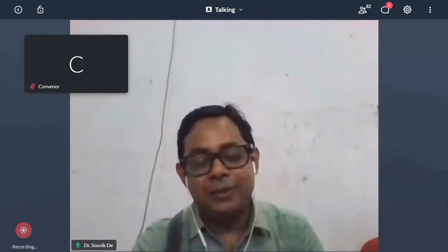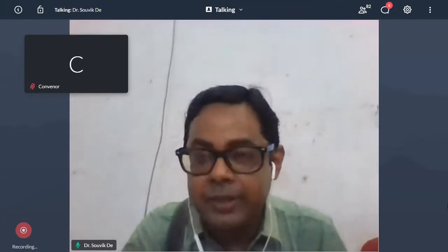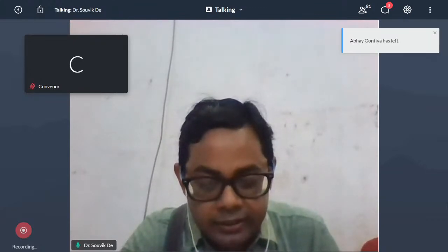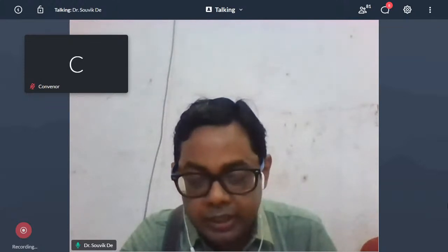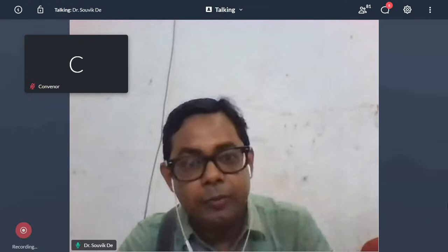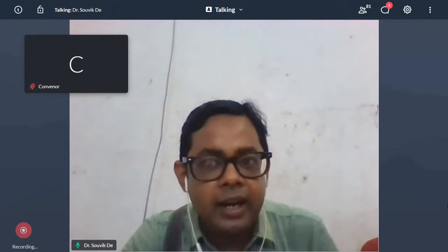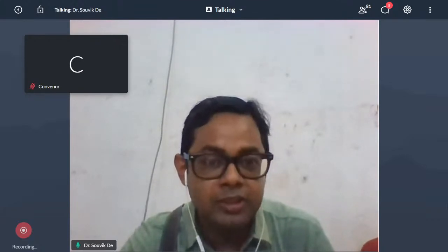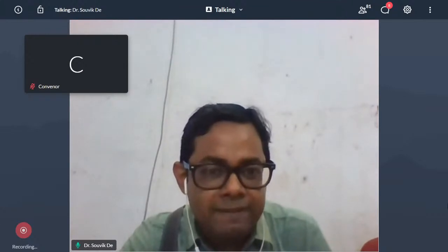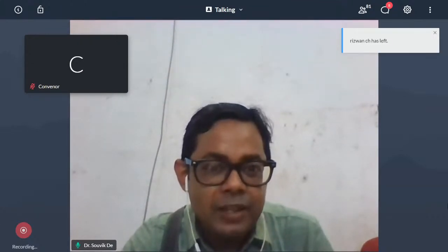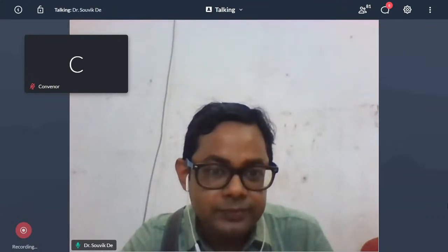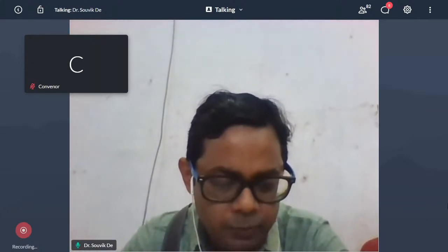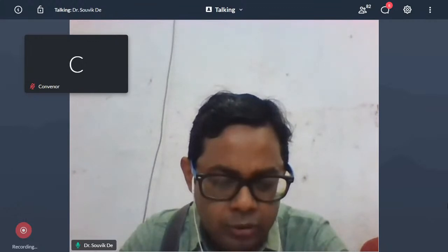Okay, that's great. Sir, I have one more question. If the participant doesn't have a question, you mentioned that nanofiltration is good for removing suspended particles as well as divalent ions or beyond. So I was just wondering, can't we use it for desalination of seawater, because it's mainly sodium chloride? No, sodium is a monovalent atom, it cannot be removed by nanofiltration. Yes. Okay.